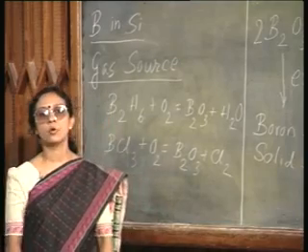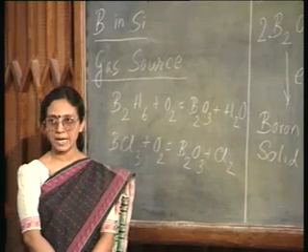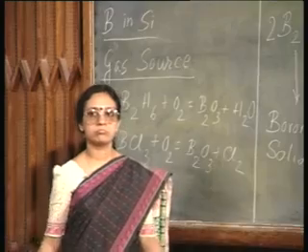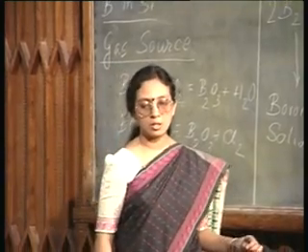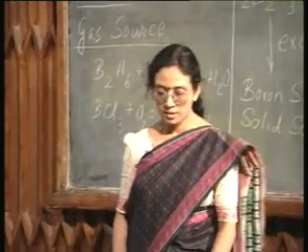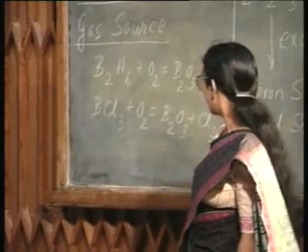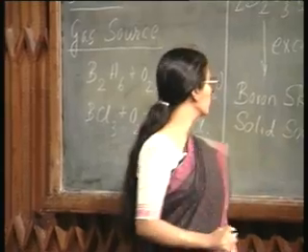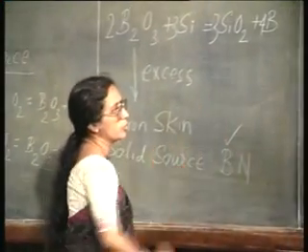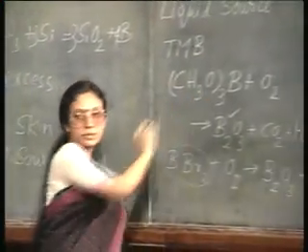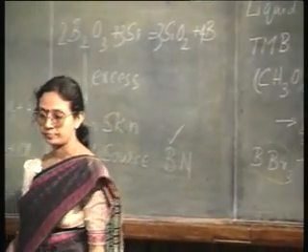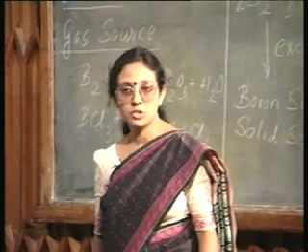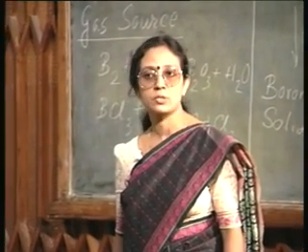But then again in small quantities chlorine is not bad, it will help in gettering. In fact, sometimes boron trichloride is used for these purposes, although the more popular sources are boron nitride and this trimethyl borate. So, these are the choices of solid, liquid and gas sources for boron.